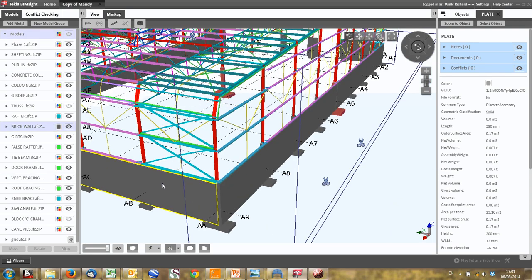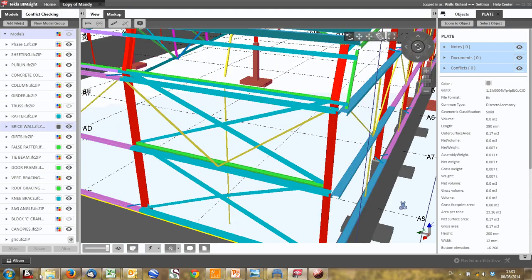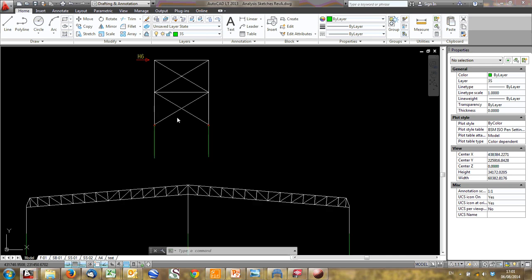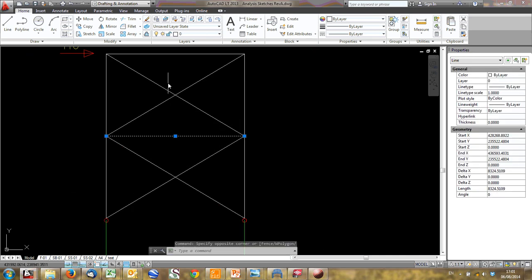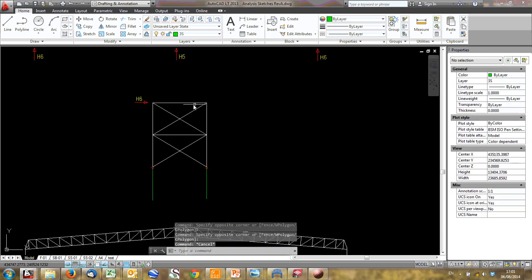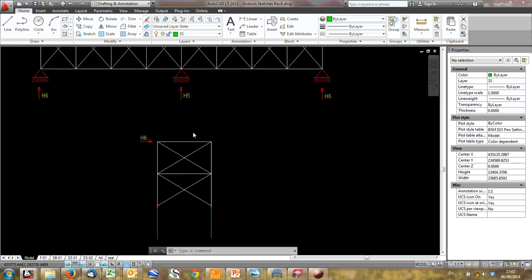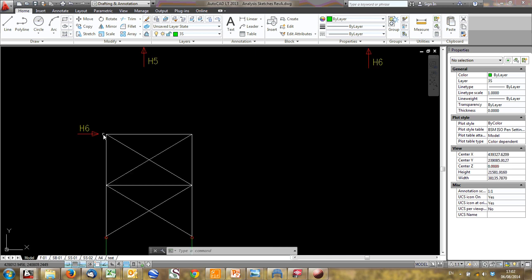So I've modeled this top part, and that'll carry the loads all the way down. In this bracing, as I said before, it's tension only, but be careful: these diagonals are in tension, and these horizontal members need to be designed for compression. So what we normally do is make them circular hollow sections, which is basically a pipe. You have a pipe here, a circular hollow section, and this can carry the load, so the load will come down in compression, tension, compression, tension.